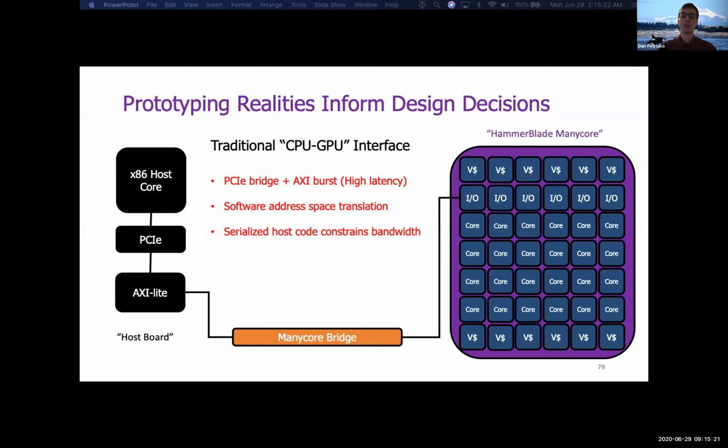However, this approach loses substantial performance through what we call gearboxing. Because of a 32-bit AXI bus, each memory request is actually composed of 4 packets. Disjoint memory address spaces means there's a separate memory management runtime, costing performance and programmability. And lastly, needing to synchronize on the far side of a PCIe bus means that bandwidth between the systems is ultimately constrained by the bus latency.